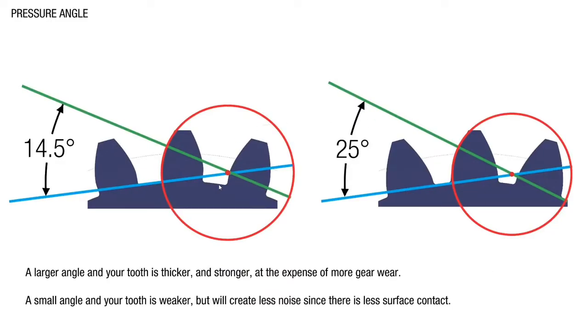Now, the first parameter that comes up inside this tool is called pressure angle. So let's talk about what that means. Basically, the pressure angle is the angle between the tangent line, which connects to the center of the radius of the top arc of the tooth of the gear, and the tangent line that is touching the inner circle of the gear.